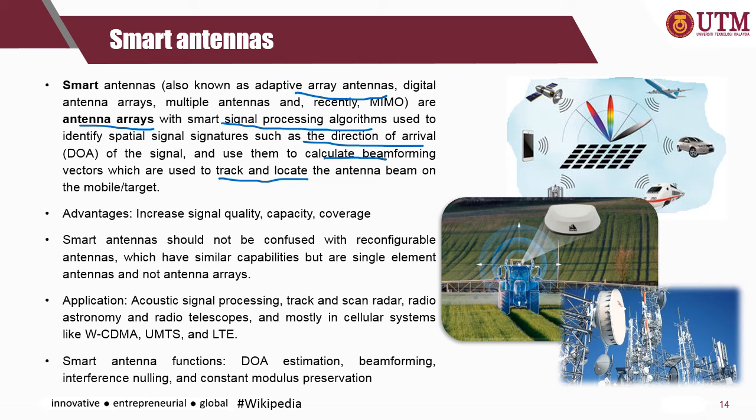It is more or less similar to reconfigurable antennas, in which the antenna can be designed to focus on an intended area or frequency. But a reconfigurable antenna is a single element, whereas the smart antenna is in an array configuration.